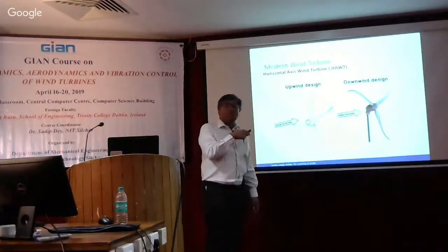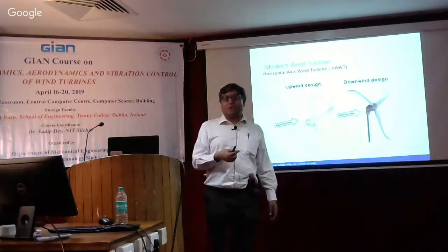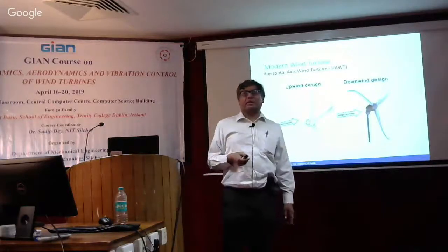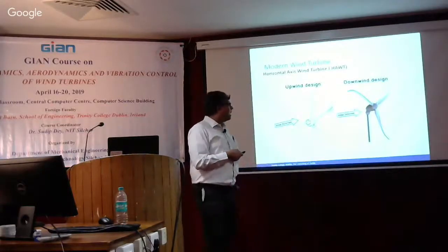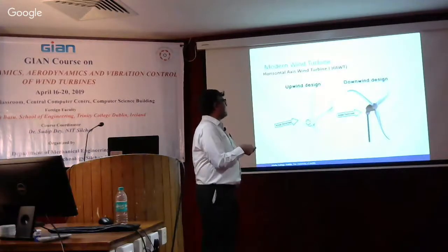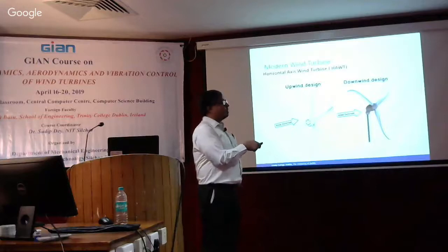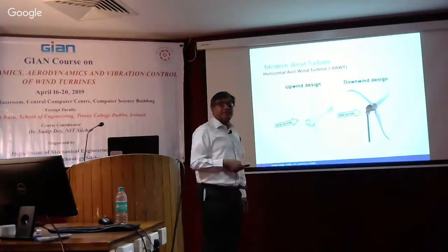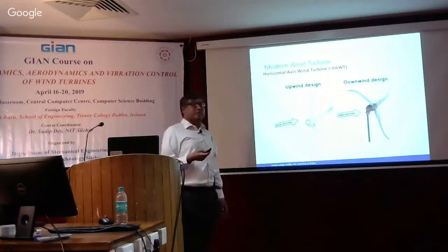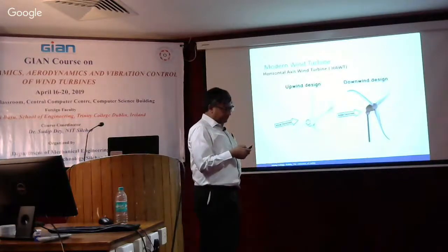And we saw a simulation in the morning where I showed how the blade was deflecting, as part of the project in seconds. So effectively, we can still have a tower shadow effect, but not as prominent as in this particular case. But really, that's the difference between the two, upwind and downwind design. What it means.